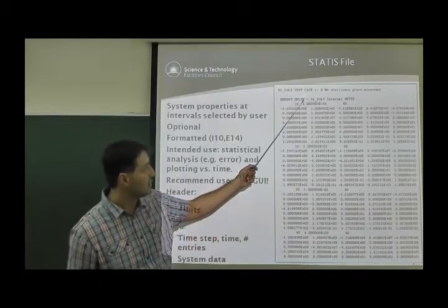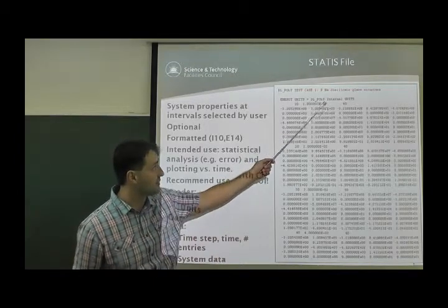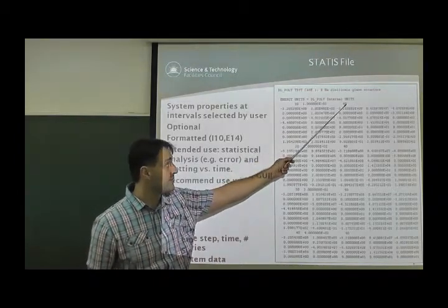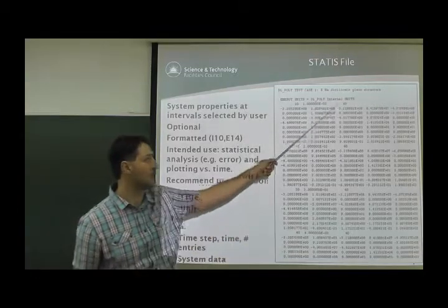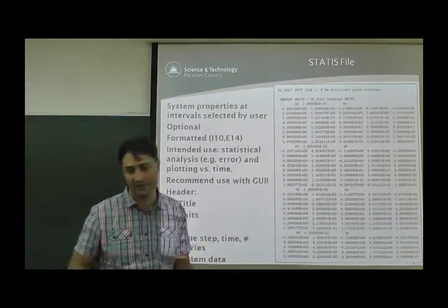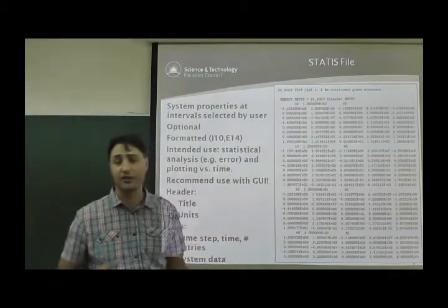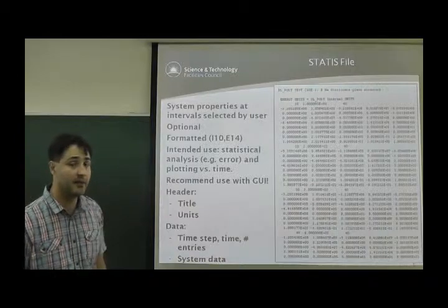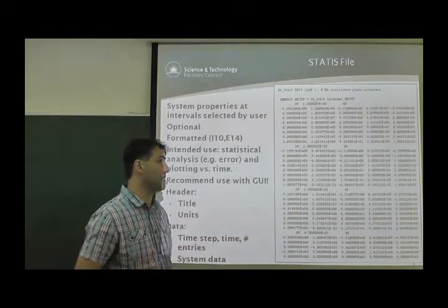This is the cumulative time, and this is the number of values that follow before you go to the next segment. Of course, this number of values is always the same for all the segments of the same simulation. However, if you write your own software to parse this file, you need to know how many values follow in order not to read extra.